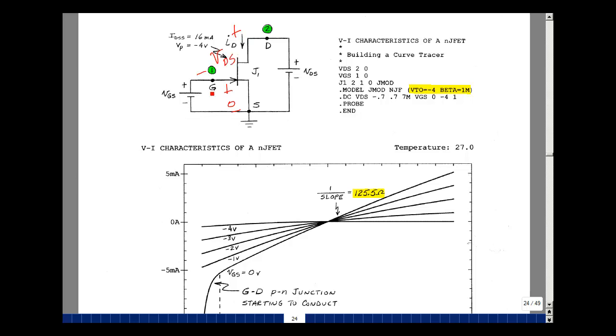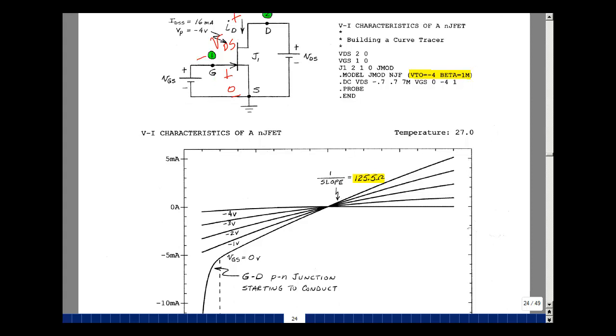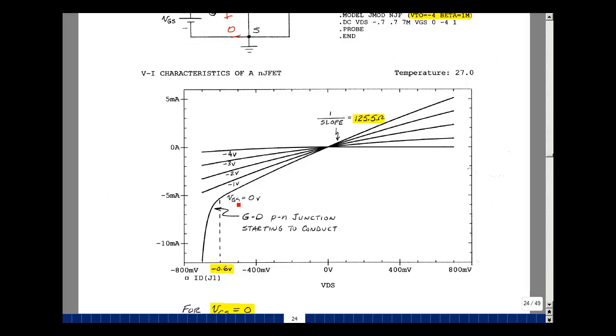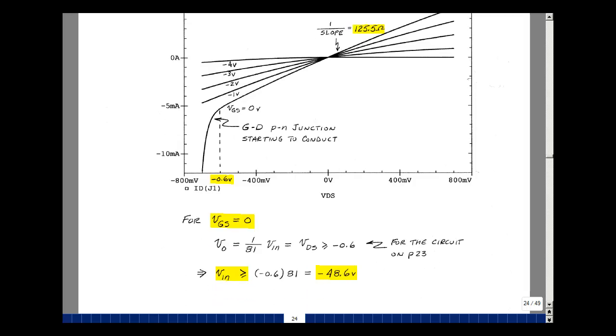And that means when that's negative, we're going to forward bias this diode and current's going to flow in this direction. Current would be coming out of the drain, going into the gate. This is a limitation of the range of voltages I can apply when they swing negative. As a voltage-controlled resistor, we're going to expect to see signals that are most likely sinusoids or things that swing positive and negative. The worst case here is the case of the gate source being equal to 0.